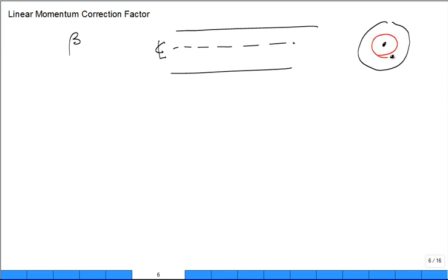So let's talk about a ring of fluid that's at distance r, lowercase r from the middle, and lowercase r goes from 0 to cap R, the overall radius of the pipe. And everywhere in that red ring, you have the same speed. True? You have some speed like this, which is the same everywhere in that little dA in that red ring. That red ring has a little area dA, which is 2 pi r dr, and it has the same speed.